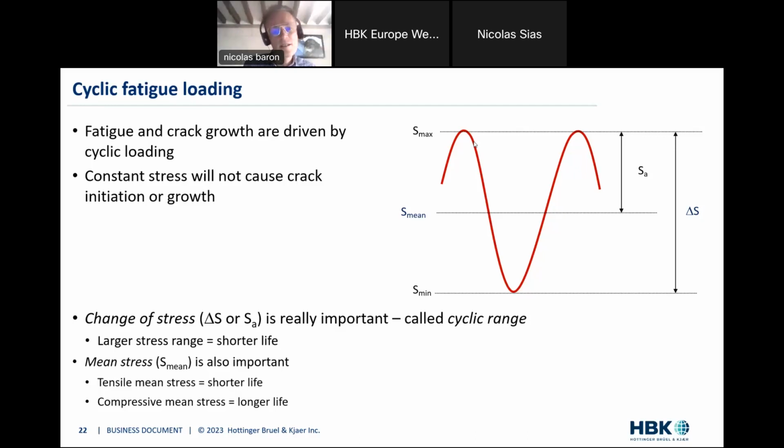The higher the change in your stress, the lower the life in your component, because your design is submitted to a big variation, and it's more difficult for the component to withstand such a high change in stress values.